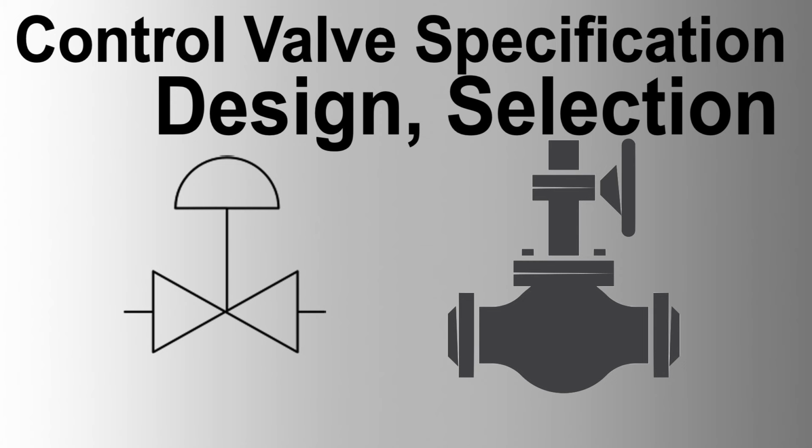2. Pressure control. Example, process gas compressors. Type of valve, pressure control valve, PCV. Design considerations, body material: carbon steel for general applications, stainless steel for corrosive environments. Trim material, hardened stainless steel for durability against erosive wear. Valve type, globe valves are preferred for precise control. Ball valves can be used for high flow applications.